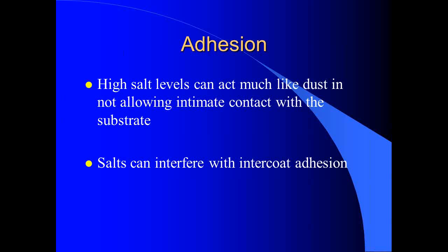Well, when they did an analysis on it, they found that just by leaving that surface overnight in that salt-laden air, it contaminated that surface with enough salt that the next coat could not get a good bond. So they do interfere with adhesion, and it can be from just overnight.